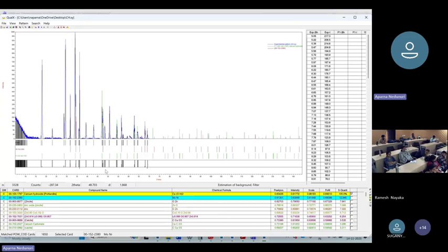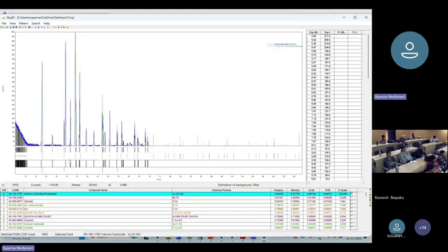Now you see over here, you have the peak positions of the peaks that are present in your sample. And if I match that one with the Portlandite, whether all peak positions are addressed, like the ones that we have seen earlier. No, right? So the Portlandite here, this peak position is matching, but this is not there, right? So this is some other peak. This is not Portlandite now.